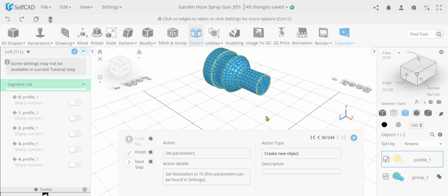Like sometimes you want to have, let's say, an arc and then a straight line. You can convert part of the polygon. For example, the arc could be a spline, and the line could be a line. Otherwise they will be losing the sharp edges. So you can do that, but the arc itself, because they have many edges, they will need to convert to a spline. That's basically the idea over here. So in Loft over here, you can see we have the correct order of the profiles. Otherwise you can switch them around, but they are selected correctly.